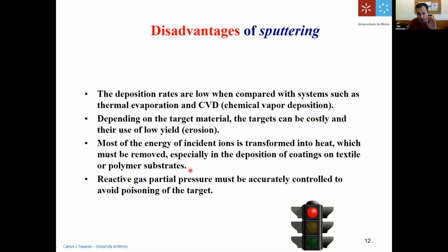It's very good to produce mirror surfaces, for example, in the optics of cars, for mirrors, even for Christmas balls. You know, these balls you can put on your Christmas tree. You can use thermal evaporation to produce very nice colors on these plastic spheres, just as an example. Or you can use it for other processes in which the coating is protected and will not be subjected to wear or erosion.